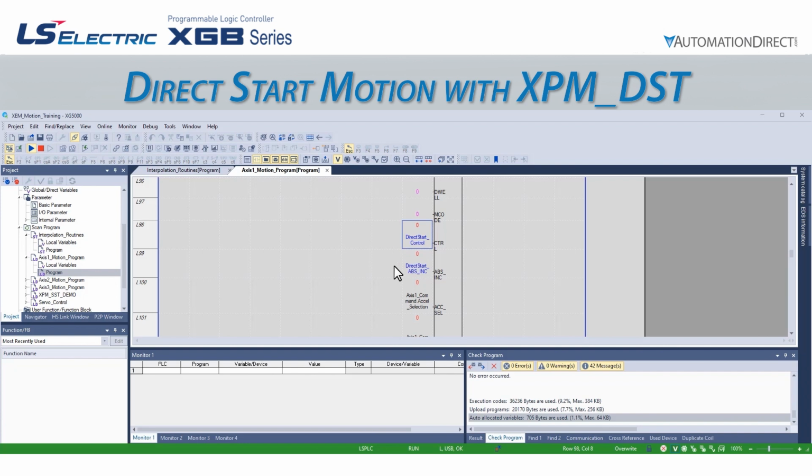We could set this to 1 for a speed move, which is a velocity-based move that requires the use of the XGM STP function block to stop motion. This function block is covered in another help topic. We could also set this value to 2 for a feed move, which is an incremental move where the sign of the target position determines the direction of rotation. Please refer to the product documentation and help files for more details on each. Our absolute or incremental bit is showing 0, so this will be an absolute move. If this was a 1, our move would be an incremental move made relative to the axis's current position.